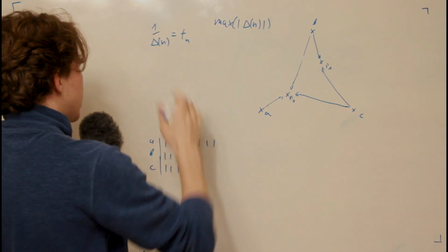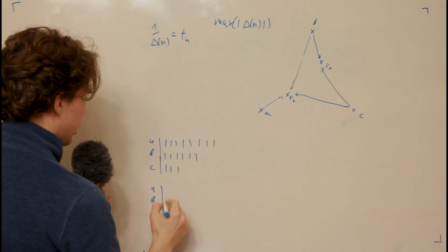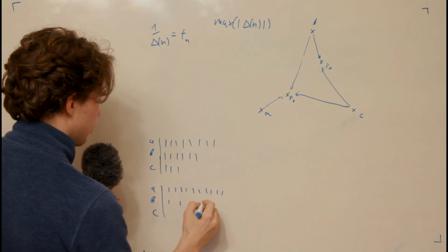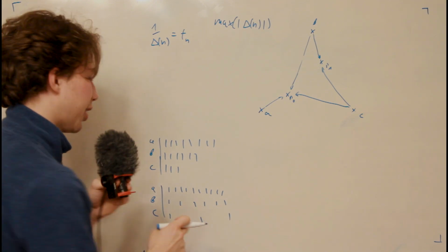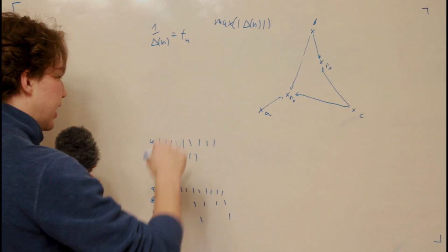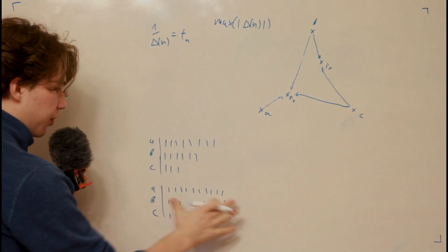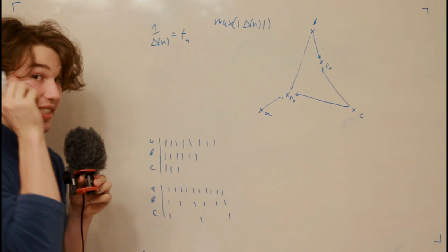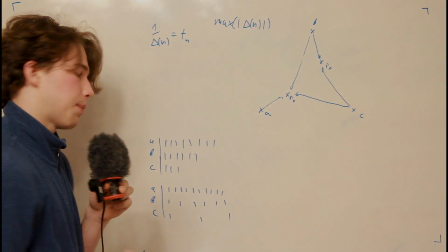So what we actually want to see is something like this. Yes, that's something we want to see. But how do we achieve this? We achieve this by changing the time in between the pulses for each motor. So within one motor, the time difference between all the pulses stays the same, but the time difference between each motor is different.